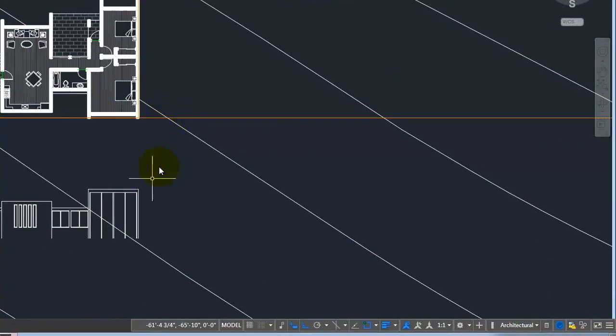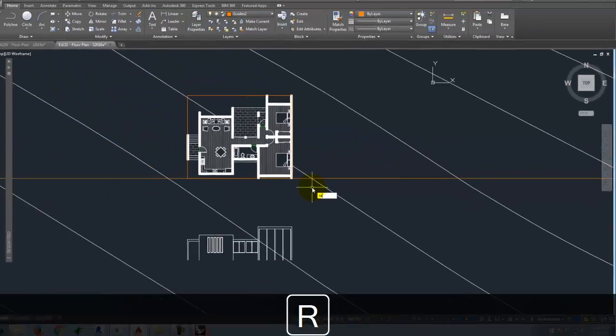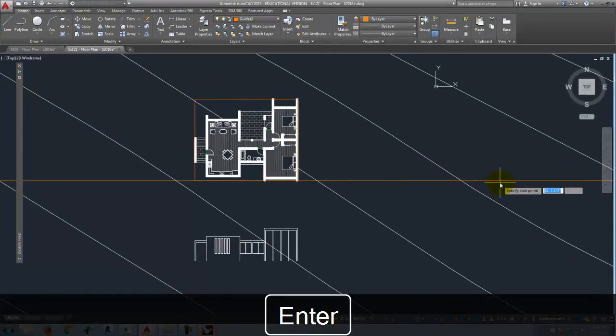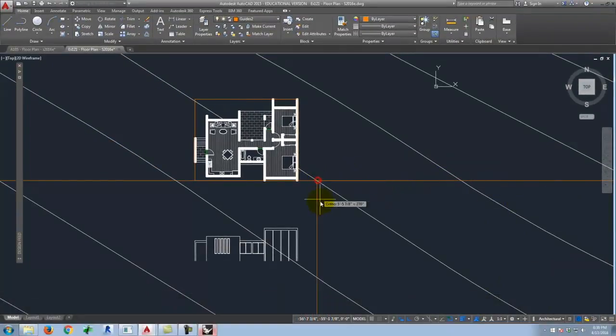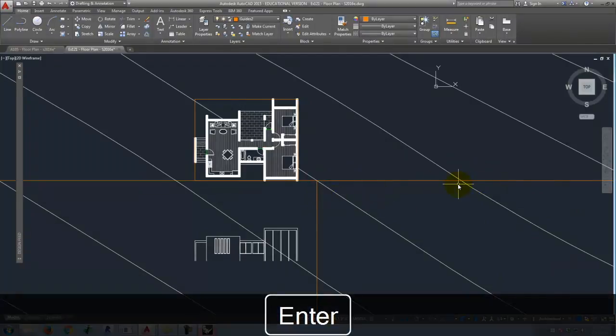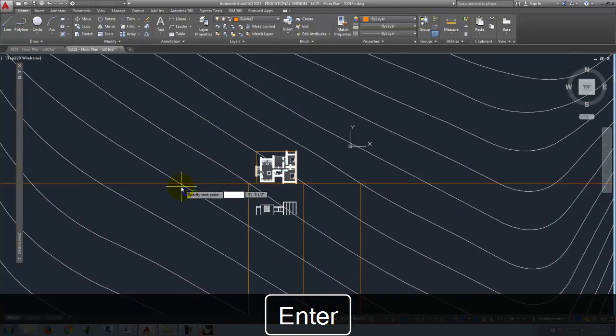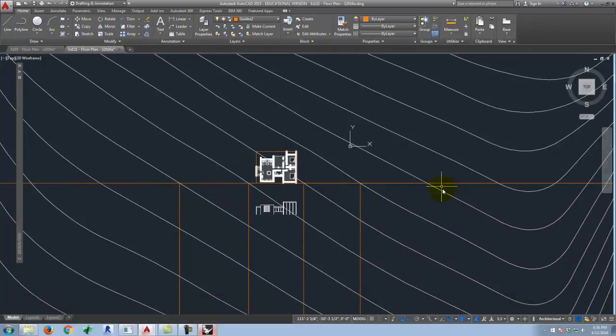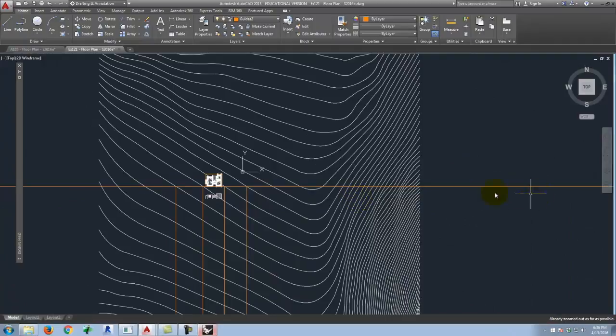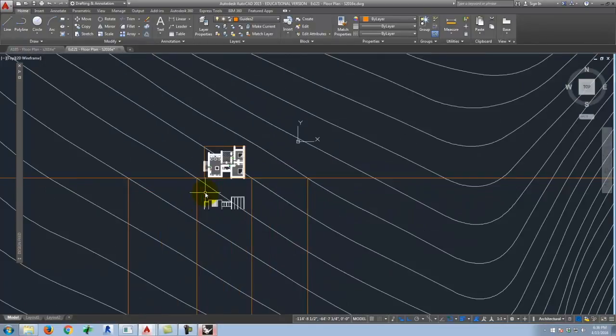And I'm going to make some vertical marks using the ray command at each place where it crosses a contour. So it crosses one right there. It crosses one right here. It crosses one right here. And it crosses one right here. And you'll have to judge how many to do. Minimum, you should do 4, right? Maximum is maybe 5 or 6, because you really don't need more information than that. As it is, this is probably too much information, but we want a nice gentle slope to this anyway.